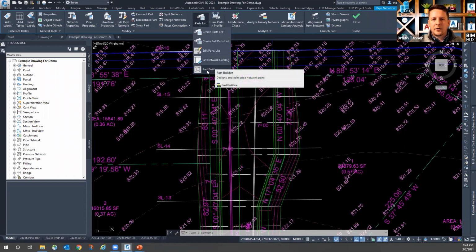Now, don't go to the part builder whenever you're connected to the C drive location. You do that, you're modifying the out of the box file. Don't corrupt anything that came installed with Civil 3D. Always create a duplicate, make yourself a backup of that original file so that if anything does get corrupted, you can recover the original information.